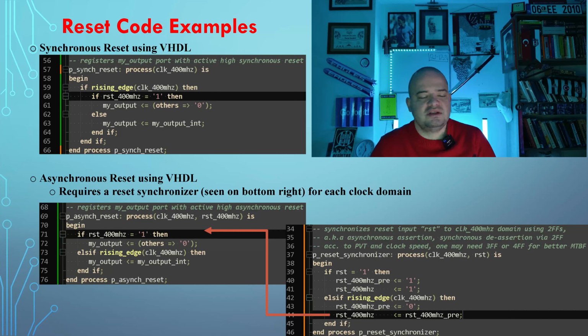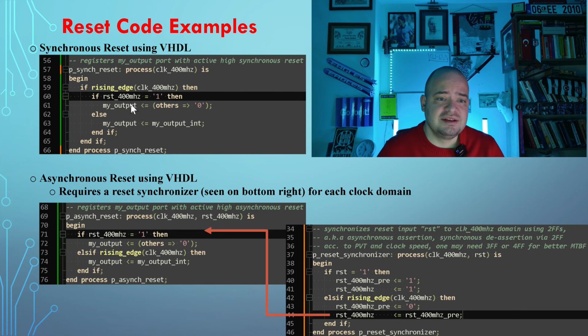If it is some internal signal in your design, and resetting the signal is not providing any benefit for you, you need to consider that, and you shall not reset those signals in your reset statements.